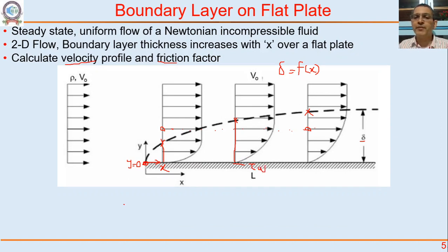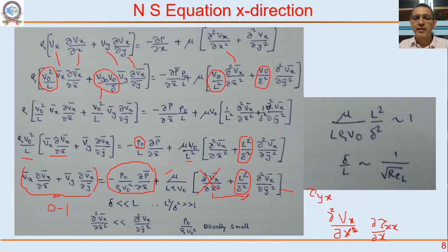So viscous stresses cannot be neglected within the boundary layer. If they cannot be neglected within the boundary layer, that means this term has to be important, has to be considered.